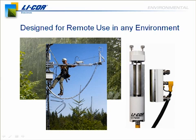That's a really good question, Jose, and I should have been more clear about that earlier. No, in fact, you do not need to put the LI-7200 in an instrument enclosure. Much like the 7500, the instrument is weatherproofed, and it's designed to be put up on the tower arm at the top next to the sonic, and you don't need to try to enclose it in anything. It's designed to operate over a wide temperature range, minus 25 C to plus 50 C, so you don't need to give it a temperature-controlled environment or anything like that.